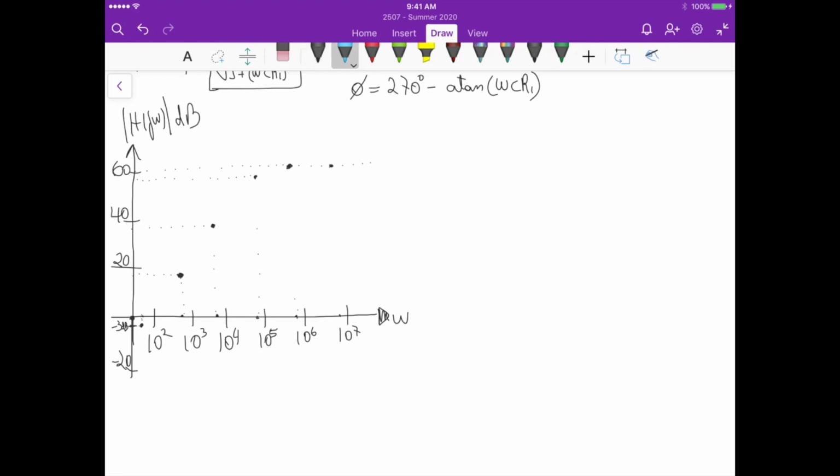and then if we plot this, we have our unity gain at around 10 Hertz, right? So this is close to, right here it's 62 radians per second, which corresponds to mostly the 0 dB, right?